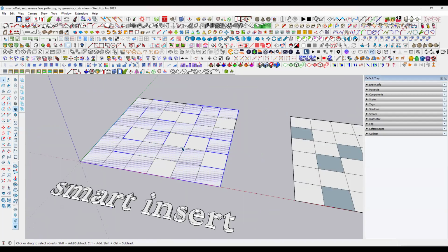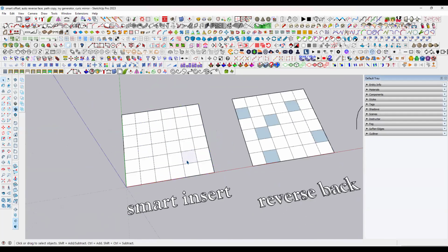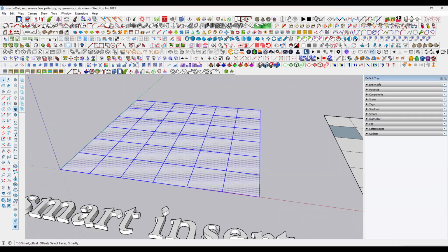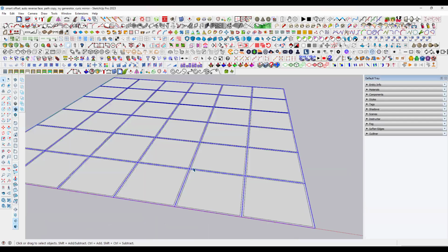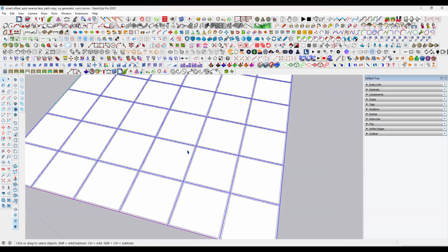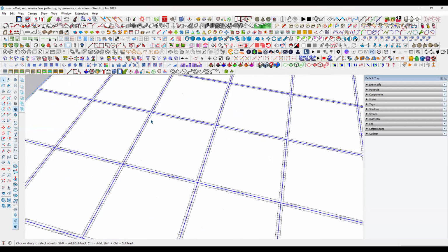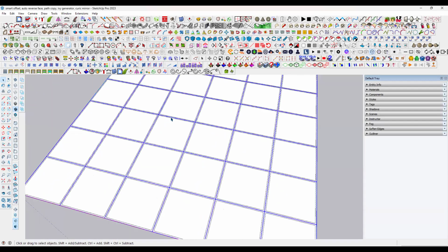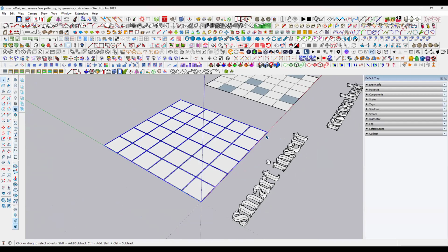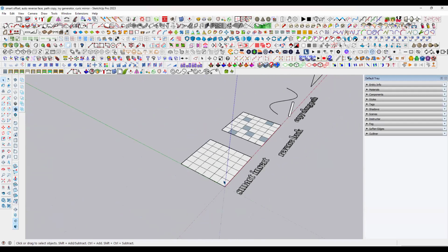Now see, the whole surface is going to be created. So on multiple surfaces it is going to be created, minus 0.2 inches I'm giving here. See what happened? Here, on the multiple surfaces you are getting the offset. With a simple one click you created this one. Then, along with that, we got a situation. With the help of this one I'll again explain one more topic.